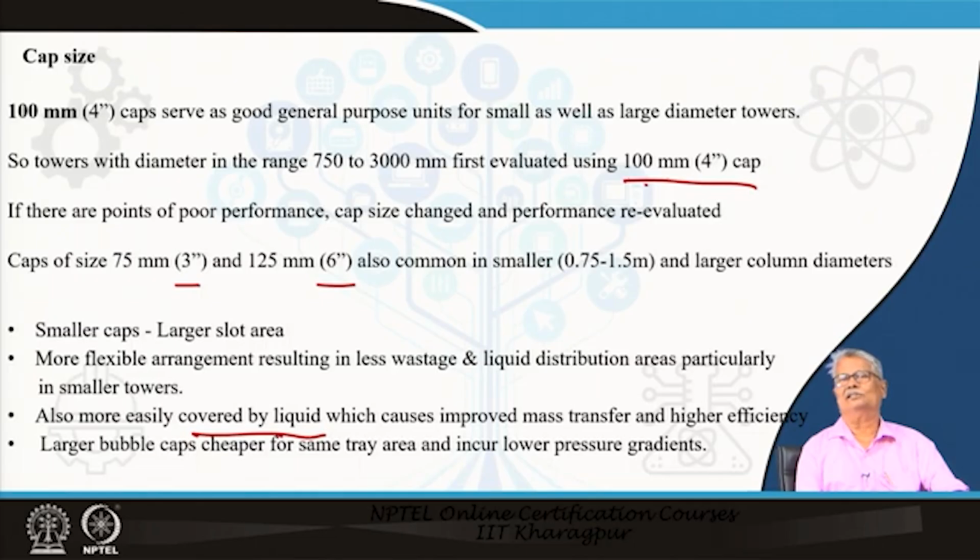But in case of large caps, normally you have a lower pressure gradient. That means you choose what size of cap you are going to use. You normally will be starting with 4-inch caps, unless you are really working with a very large tower or a very small tower.